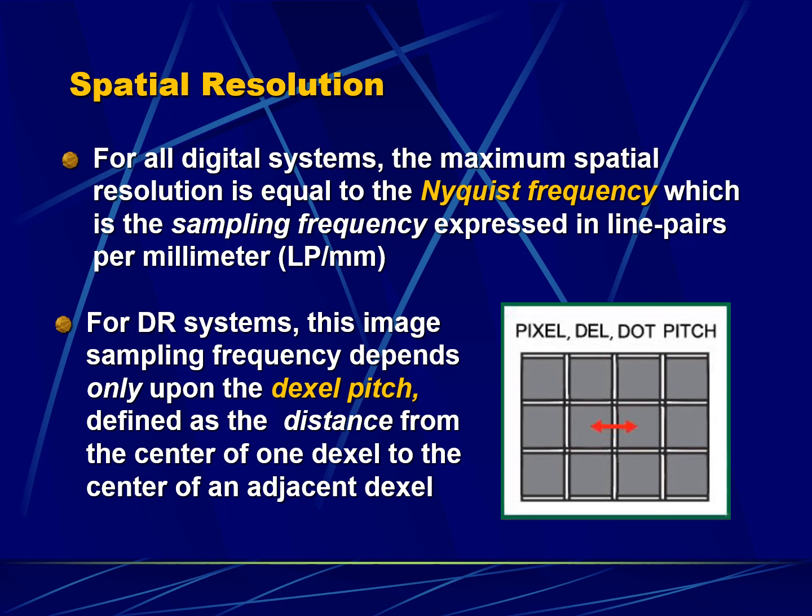So for any wave, crest and trough, you have to sample that wave. One wave has to be sampled at least twice. And that means the sampling frequency. So if you're trying to duplicate, let's say, a 5 hertz sound wave, you need a sampling frequency of 10 hertz. That is, you need to sample every wave twice. Otherwise, you're going to get an interference pattern in your sampling as you're converting the analog.